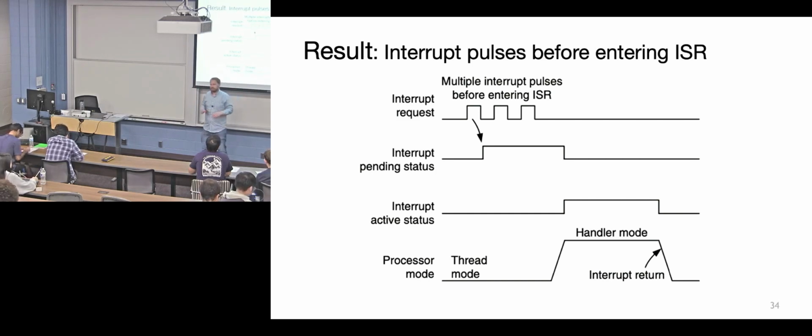What if these are 3 different interrupts? Oh, we'll get to that. Now we're only looking at one at a time, but we are going to talk about how different peripherals could provide different interrupts. Then you'd have a different interrupt request line for each one of those peripherals. If we go back to the NVIC with all the arrows coming out of it, those would each be different, and we'll talk about how to deal with those cases in a little bit.